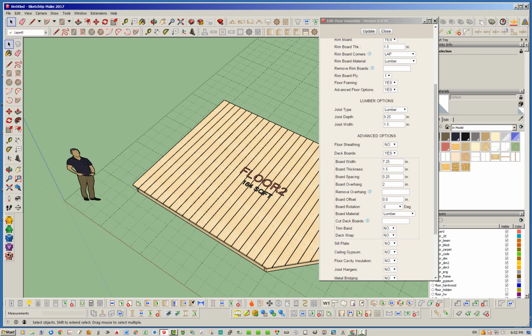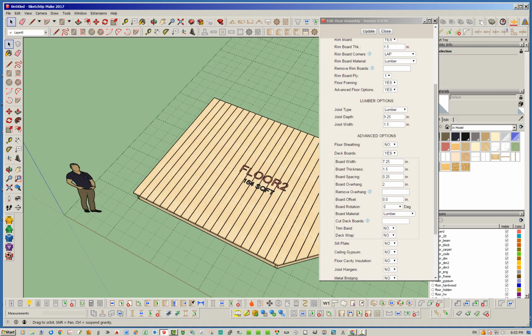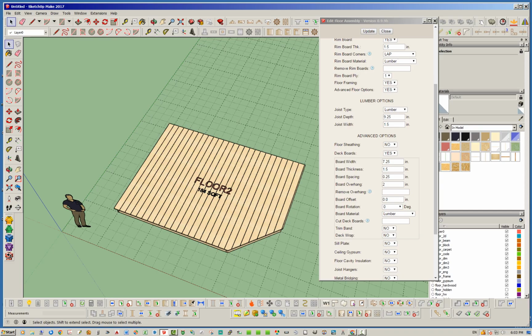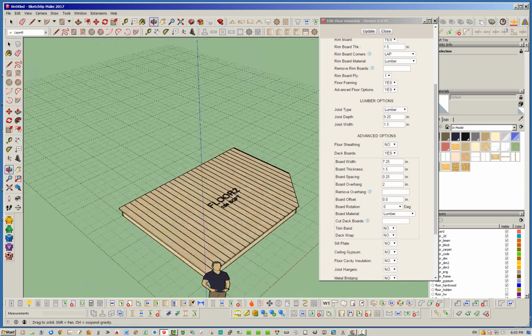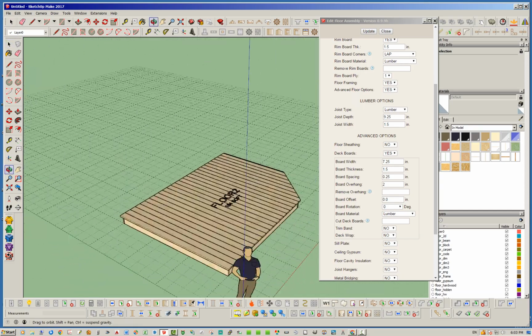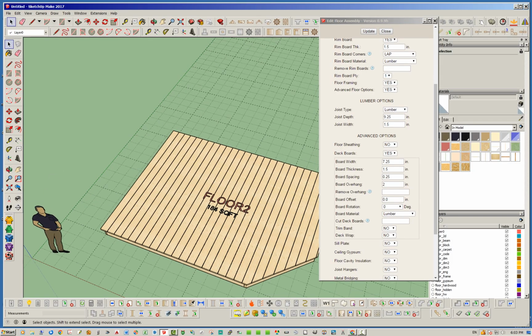when you first lay out this floor, if you're clicking the points, it will lay out the points based on where you started. But if you're using a face, of course that's not the case. You'll have to probably jump in here and figure out which side you want to turn those overhangs off on. So anyways, let's go ahead and turn off the overhang for sides 4 and 5. So you just type in 4, 5, separate those with commas. No need to put spaces in there, and we'll go ahead and update that.